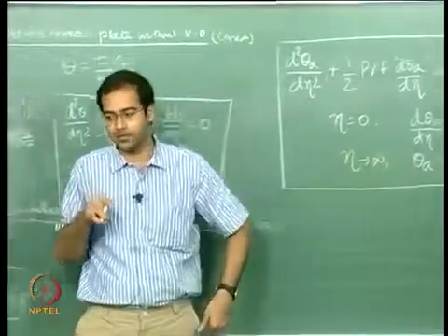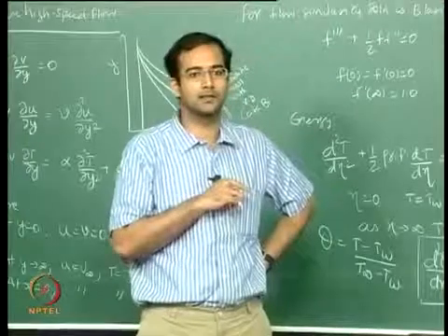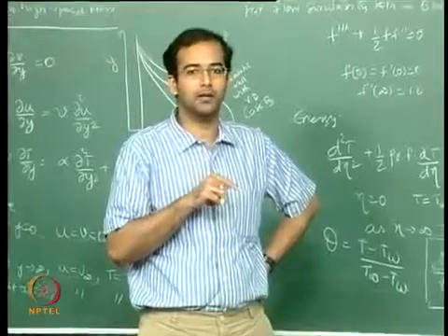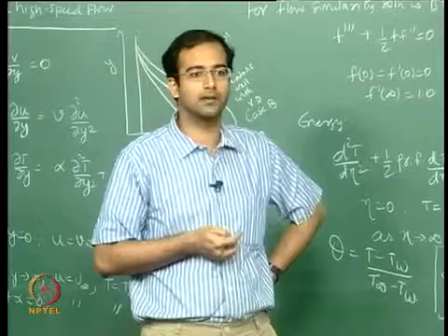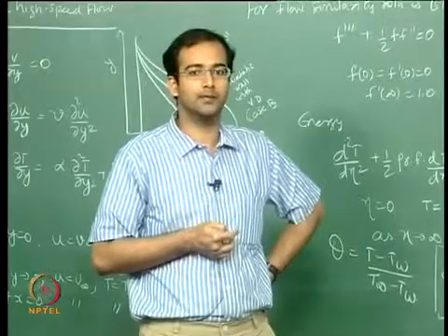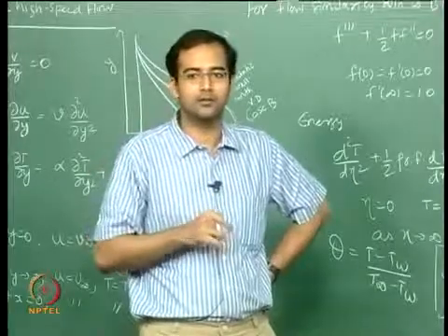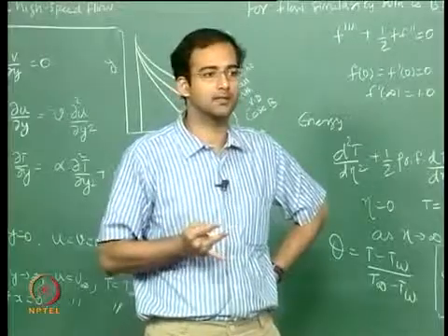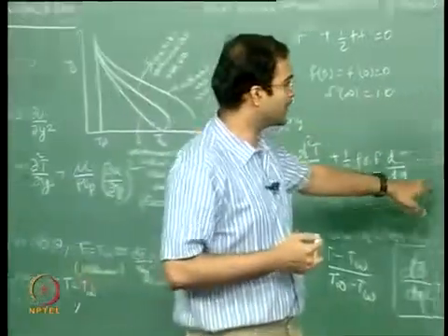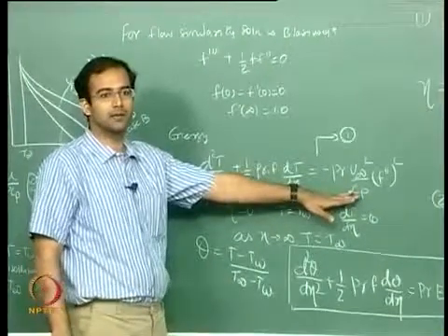Okay, what I meant was that Pohlhausen guessed that he could derive a similarity equation for energy. Because he found for Prandtl number 1, u by u infinity is exactly equal to theta, and both the equations are similar. But that doesn't mean that for Prandtl number greater than 1 the form of eta will be different. He used the same eta only, and he found that it still gives a similarity equation. So here also, when you put in your eta, finally it comes to this, which is still a similarity equation.